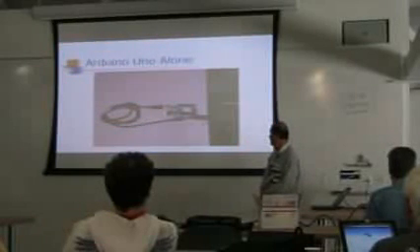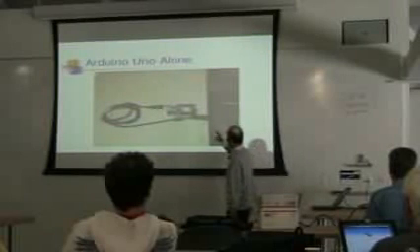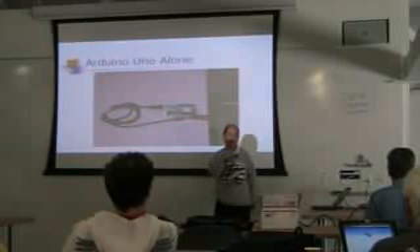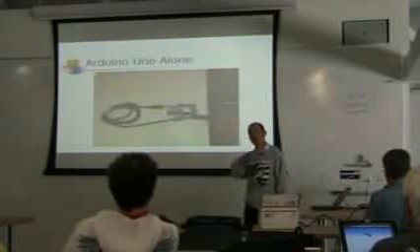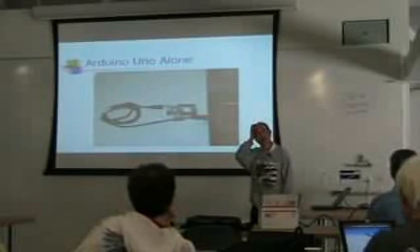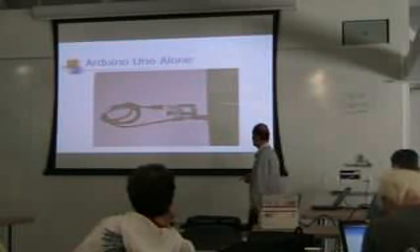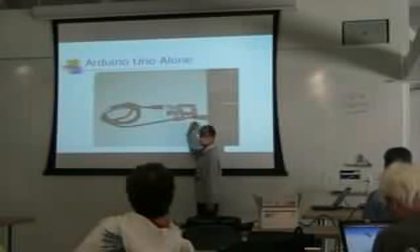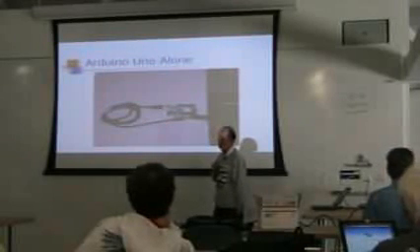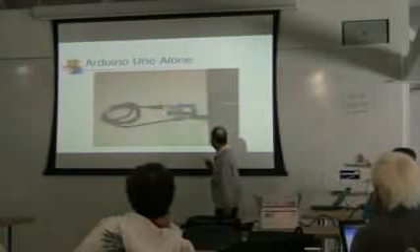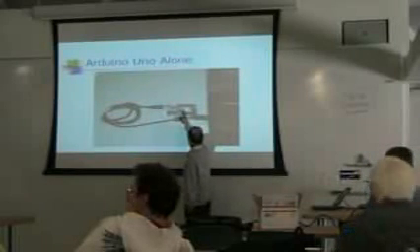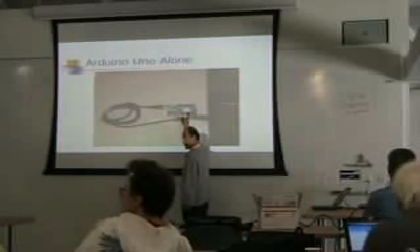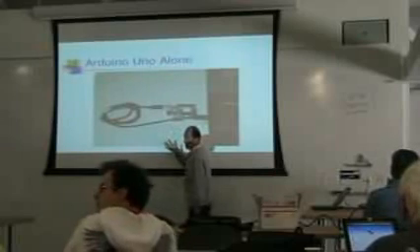And when I do the Forth system, I just take over the bootloader entirely. So I have some code in the bootloader, so I can write new code in the flash. But without taking over the bootloader, you really cannot write anything in the flash. So if we use the Arduino, we have to have the bootloader there, so you cannot write new code into the flash. And that was the problem.